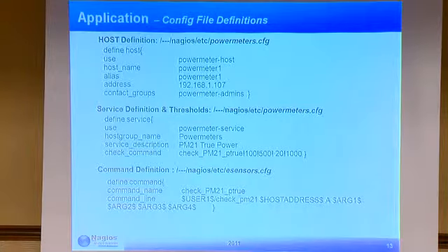So how it works is that any value between 100 and 500 is considered status OK. Anything between 20 and 100 is considered a warning low threshold, and anything between 500 and 1000 watts would be considered a warning high threshold. Anything above 1000 watts is something like an overload, so it would be considered critical high, and anything below 20 is something wrong. Probably the device is not even turned on, or the UPS isn't taking enough power, so it would be considered a critical low threshold, and so on.